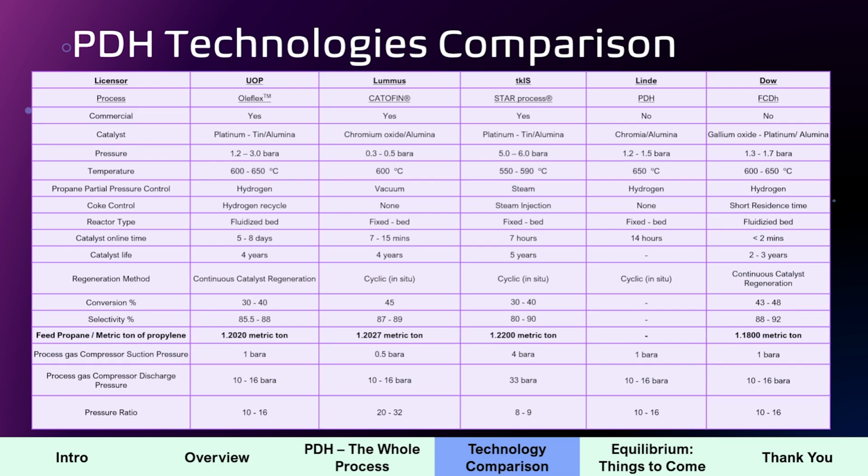Because that catalyst, irrespective of which technology we're dealing with, all of them make carbon, and all of them have to combust that carbon using air. So it's very highly exothermic. So the chances of local temperature spikes, where sintering or permanent destruction of those active sites happens, are high. So do not expect 100% across the whole 5 years.